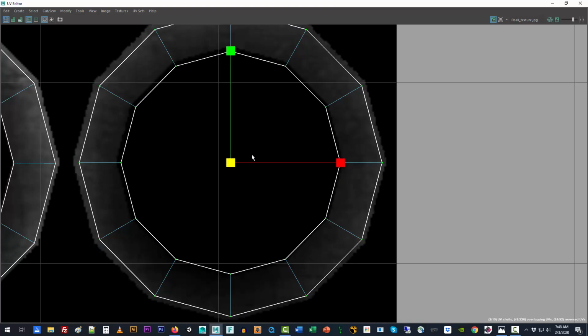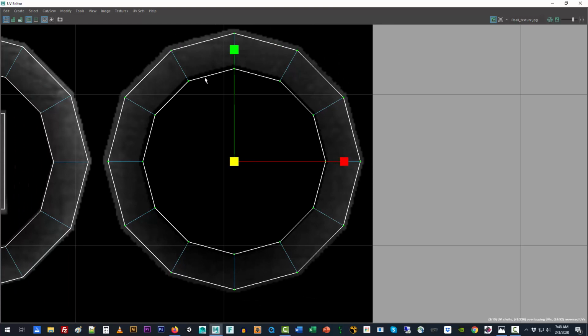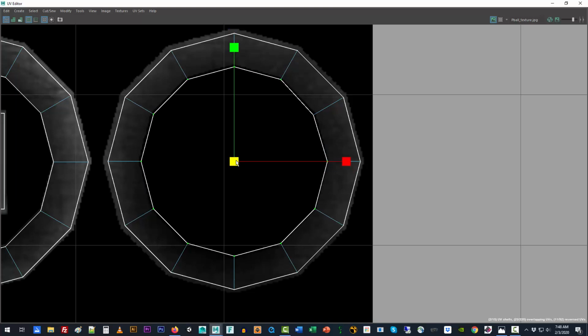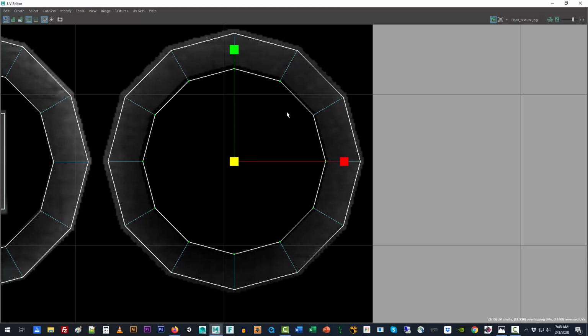It looks like I can't quite do it because I'm either sacrificing this inside ring or I'm sacrificing the outside ring. What I can do in that case is just go again to UV selection mode, select all of these interior rings, and this is just me trying to be fastidious, and so I didn't grab the top one, and just scale them all up so that all of them, oops, I didn't grab that one.